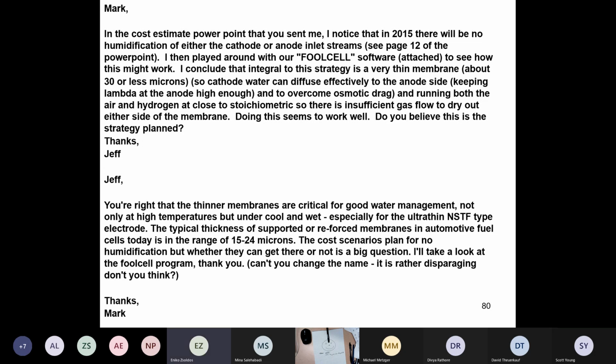I see. And are all commercial fuel cell cars made with a polymer electrolyte membrane for proton conduction? Yes, as far as I know, that's the case. Okay. Is there a cost advantage or an efficiency advantage there? Oh, by far. I mean, it's just an operational thing. How would you do this 600 or 700 degrees C fuel cell in your car? I see. Okay, I didn't realize the temperature was that high. That would be sort of awful.